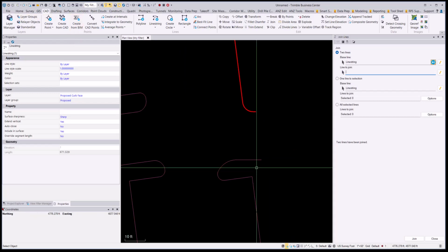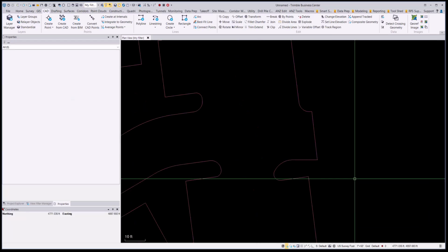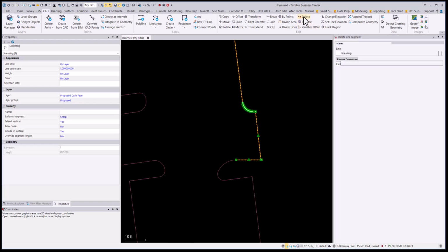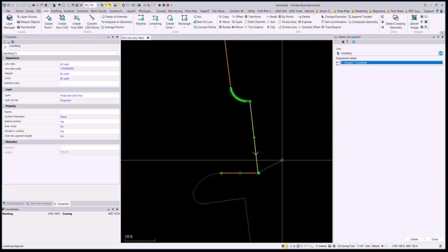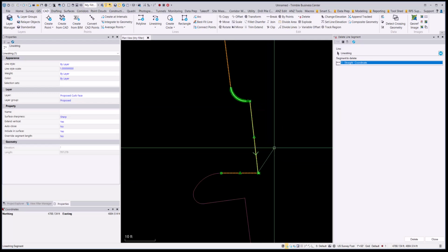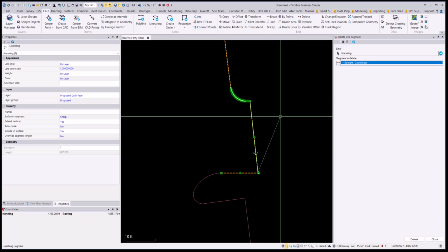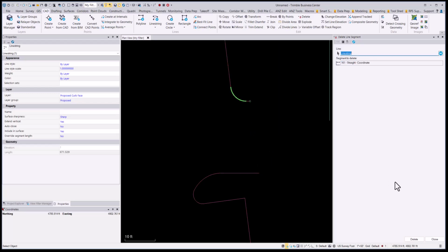And actually there's another command. If I did join across here, close that out, so now I have accidentally closed that. There is another command under the CAD tab that is delete segment, and I use it quite a bit. So if I go delete line segment, it's under the CAD edit group. Once you find that area, it's asking which segment, and if you get the green arrow, that means that's the item it's going to delete. If I pick it, you'll see it'll remove that segment out.